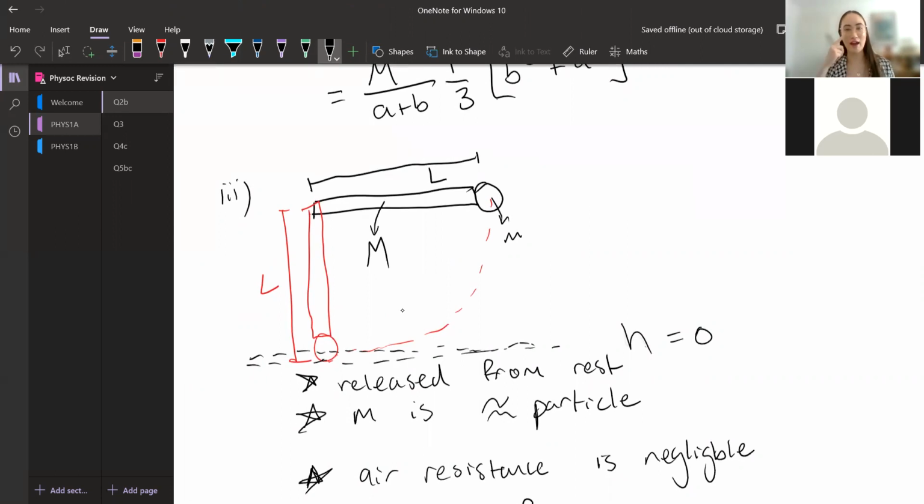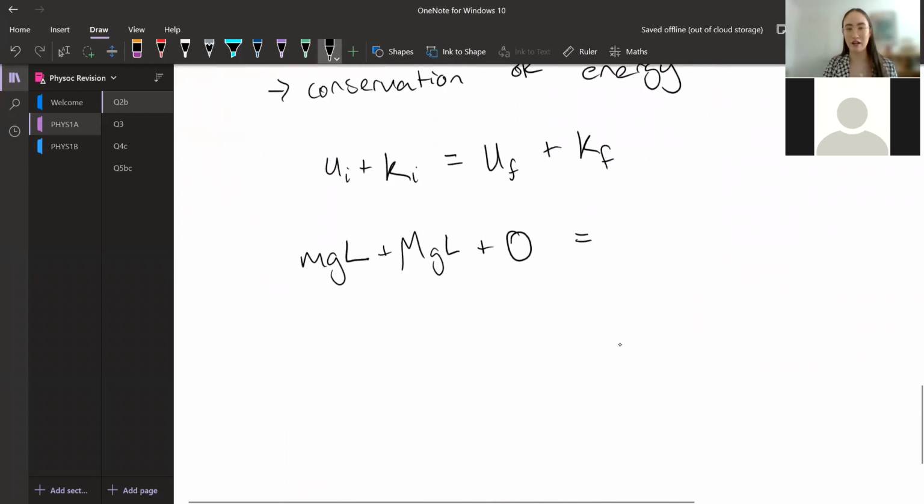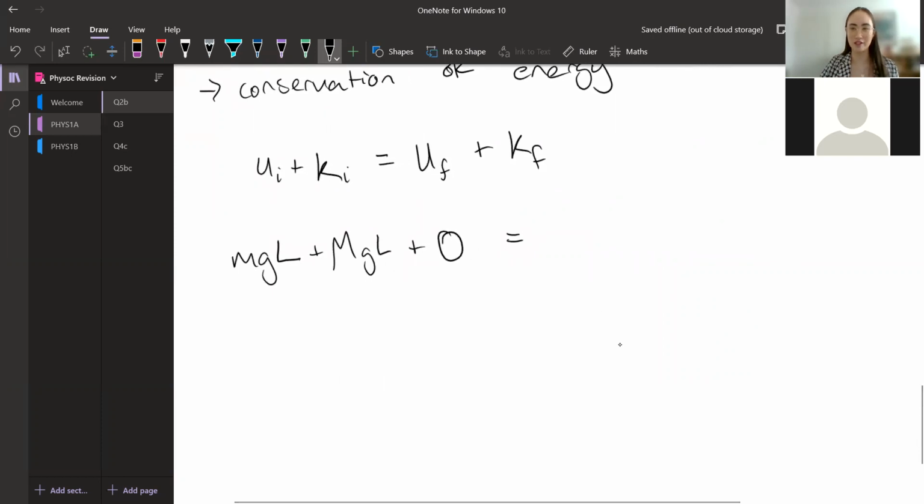In this case, our gravitational potential energy, that distance value, we measure that from the gravitational center of a rod. So in this case, it's going to be the center of this uniform rod. And now above this datum line, this is going to be L on 2. And so that's our parameter that we put into our potential energy equation of just mgh. So in this case, mg L on 2.